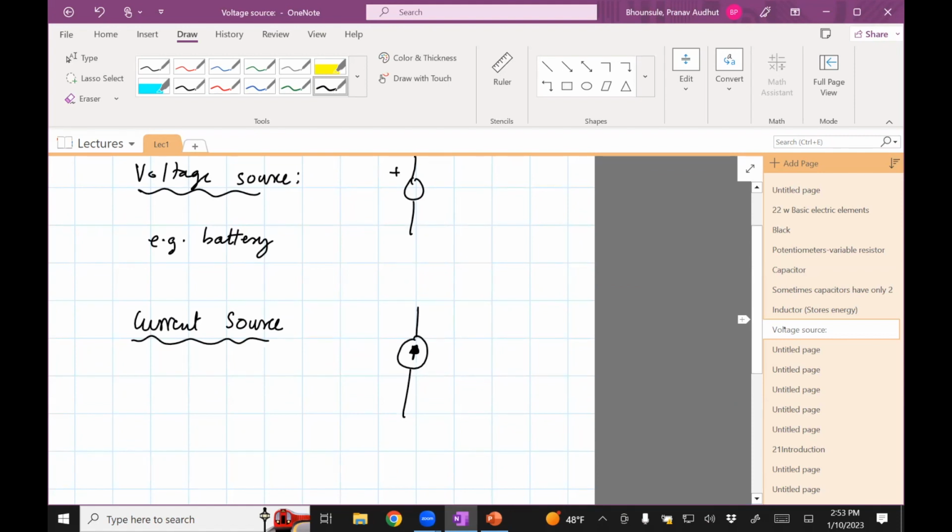If the voltage is infinite, then you can basically have a current source. You can get a good current source by using a power supply which has a voltage knob and a current knob, by setting the voltage to infinite or maximum, and then you can just limit the current to whatever you want. That will be your current source. And vice versa for a voltage source: you'll move the current to infinite or the maximum possible, and you'll keep the voltage to whatever you want. That will be a voltage source.